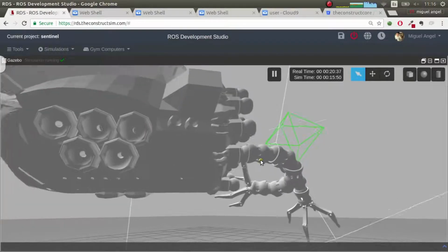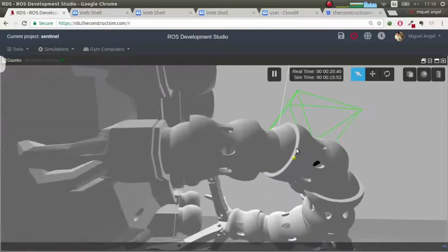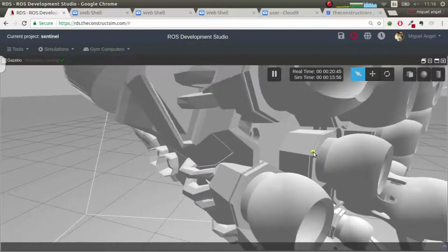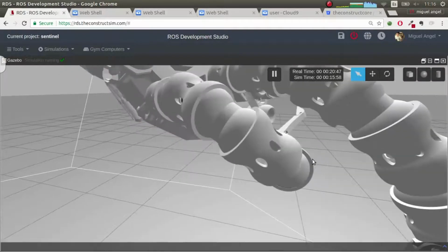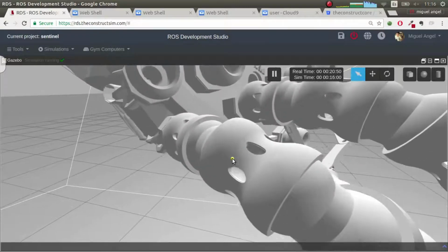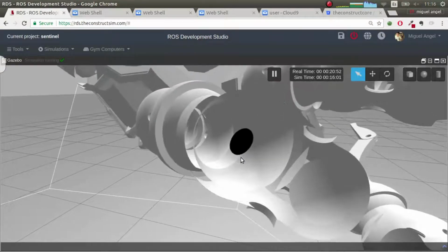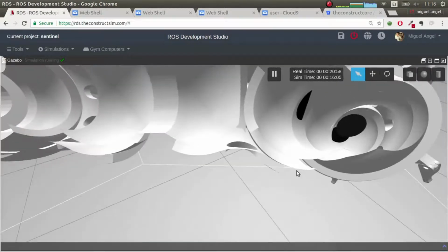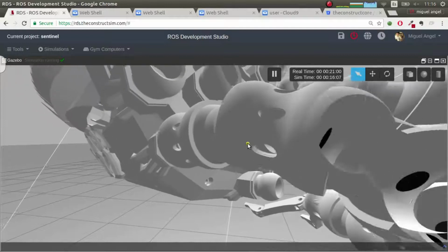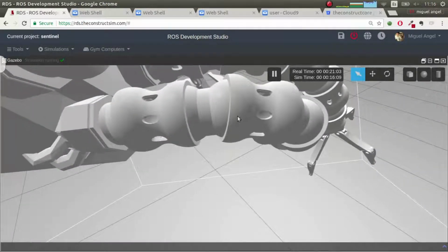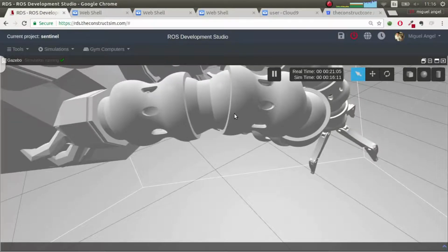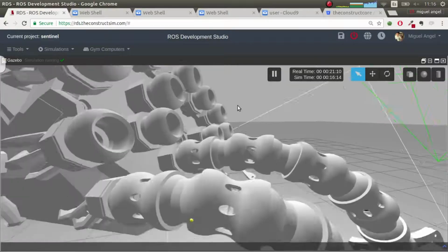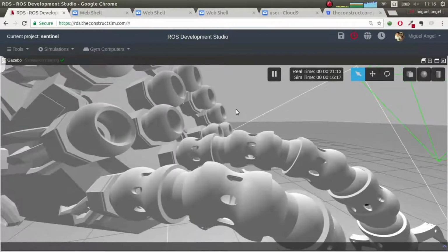If we go here and go inside, you can see those cylinders, because I prefer being able to see all the elements I generate. So you see here that there's a black disc. This is the auxiliary link that allows us to turn these joints into spherical joints, which physically they are spherical joints, but in Gazebo you have to do them with a roll and a pitch combination.